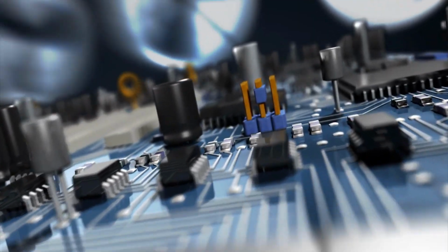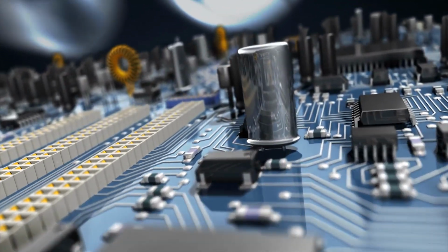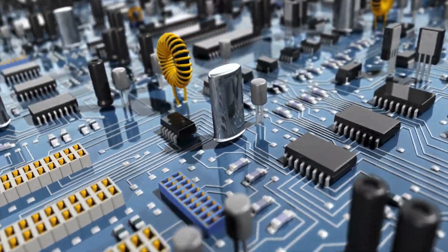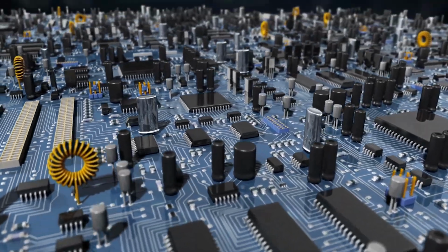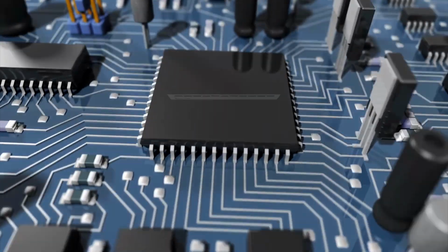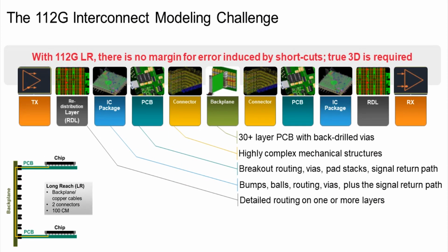Accurate 3D modeling is required for very complex systems found in recent designs to allow for structural optimization and high-speed signal compliance. In particular, high-speed signals such as 112G SerDes interface must have a solid interconnected design. However, conventional field solvers have limitations in analysis speed and capacity, and the engineers have to simplify the structure or divide the layout into several segments to run within the constraints of the machine environment.